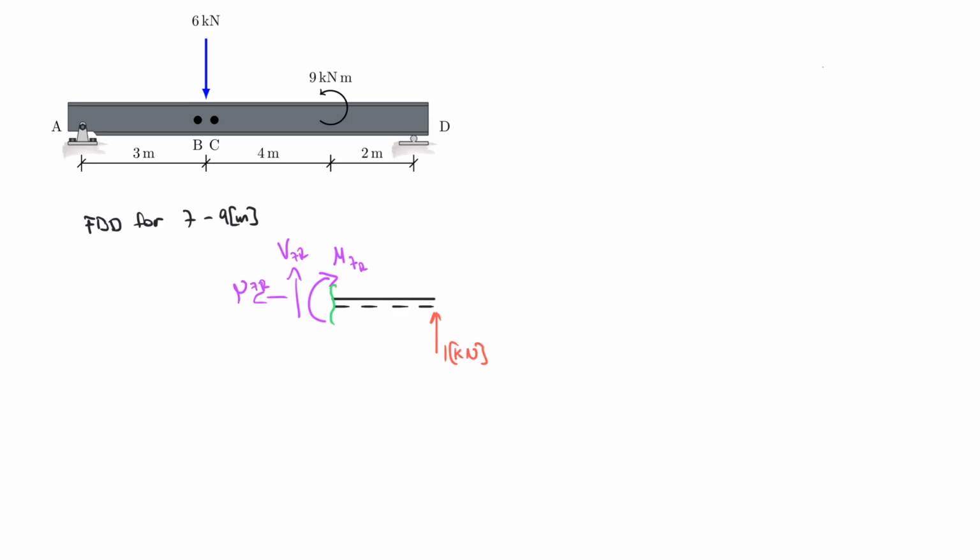All right. And please note that I always, when I draw a free body diagram, it's always including the entire either right side or the entire left side. So I don't want to have a free body diagram that is somewhere dissected from the middle that doesn't include everything to the right or doesn't include everything to the left. You can technically do that if you really know how you do it and what you do, but for this beginning purpose, it's not a good idea to do that. So for now, always include either the entire right part of the structure or always the entire left part of the structure. So before, for B and C, we used the left side. Now I'm using the right side, and therefore I have a different cut.